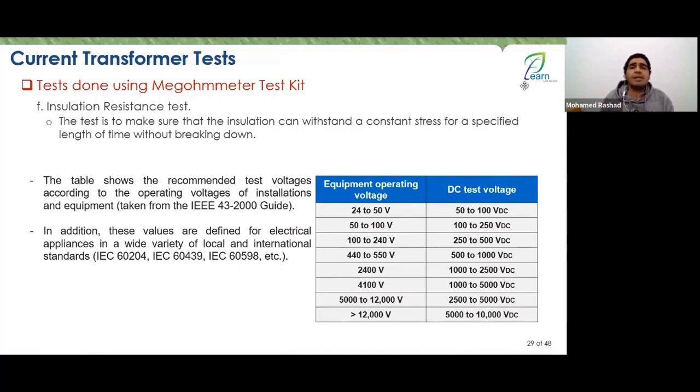First, you might ask, engineer, why are you injecting DC? Well, this is also an important piece of information that some young people might overlook or not pay attention to. The idea is that DC gives you constant stress on your insulation, unlike the varying stress that occurs due to the AC wave.